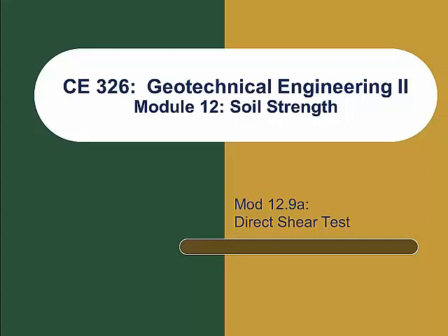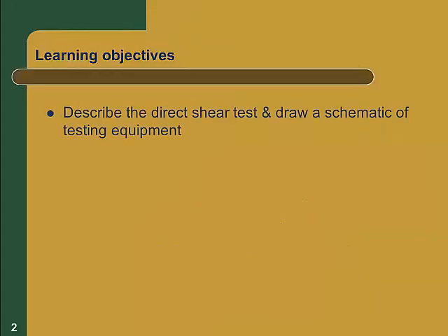This presentation is on the direct shear test. When you finish this presentation, you should be able to describe the direct shear test and draw a schematic of the test equipment. In addition, given data from a direct shear test, you should be able to properly plot the data and determine the strength parameters for the soil which was tested.